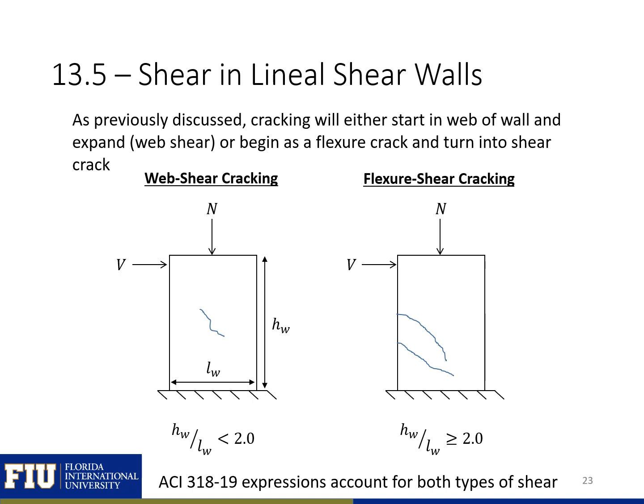On the next few slides, we're going to look at how to calculate the shear in our lineal shear walls. So as previously discussed, cracking is either going to start in the web of the wall and expand, which would be web shear, shown on the left, or it's going to begin as a flexure crack and turn into a shear crack, or flexure shear cracking, shown on the right.